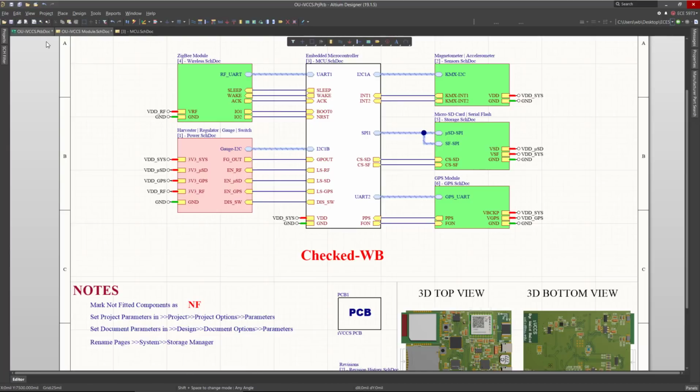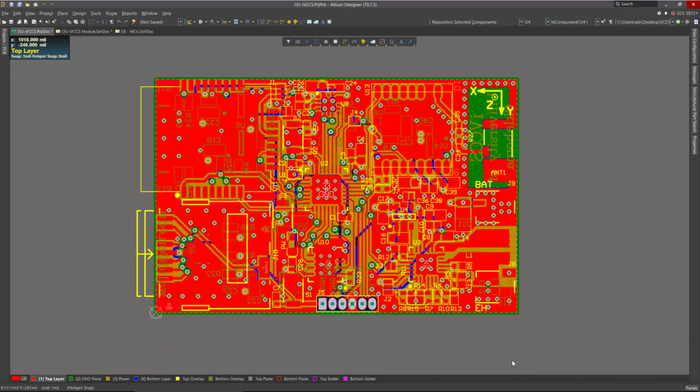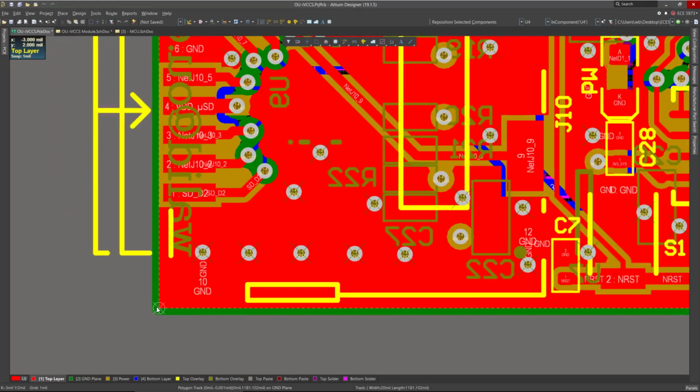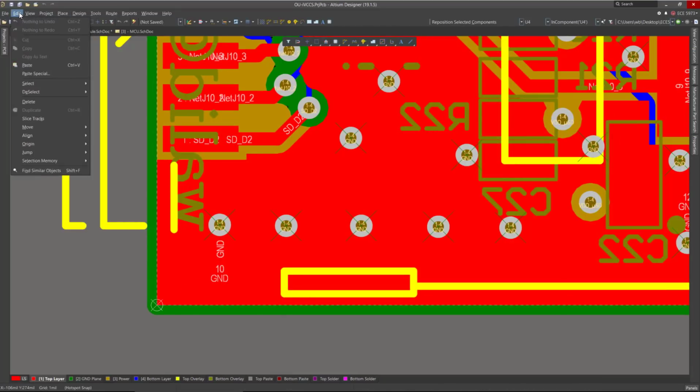If you go to the layout, now let's move away to the free space. The free space is the place where there are no components or traces, vias, or anything that has to do with the PCB layout. So if you move in here, what you can see is also the coordinates of your mouse relative to the reference point. The reference point is basically this. If we come closer, this is the reference point, and usually it's set at the bottom left side of the board.